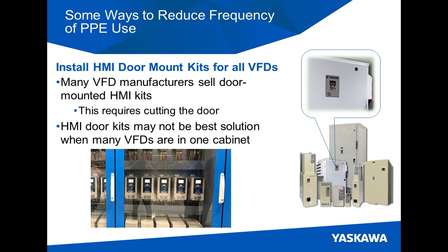That means you don't have to open up, say, the enclosure where the VFD is actually placed to just check some status or look at the product or to see a fault code. You may only need to put on some safety glasses or some lightweight personal protective equipment to do those basic functions.